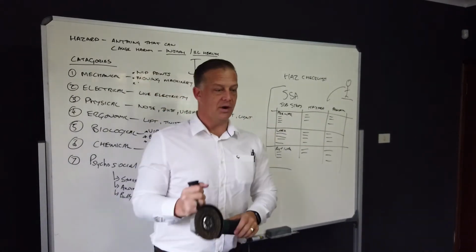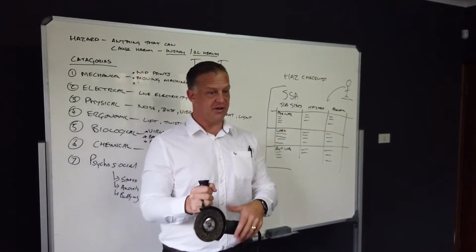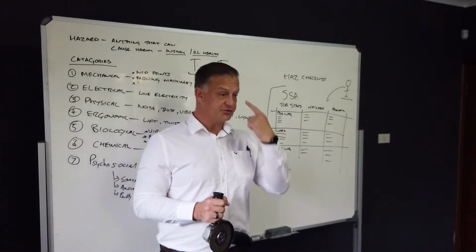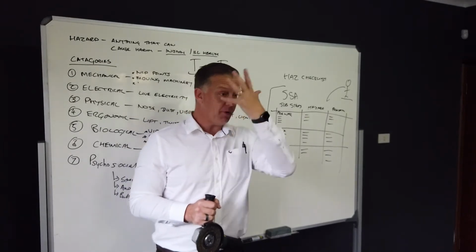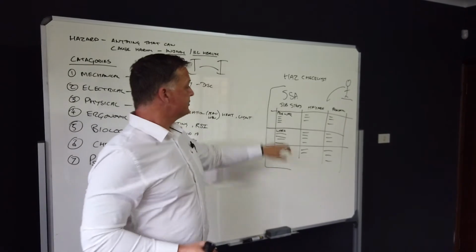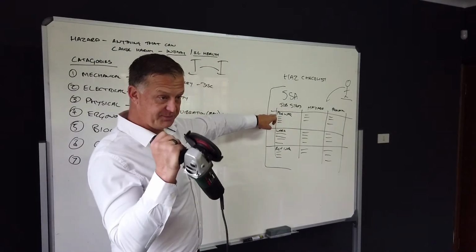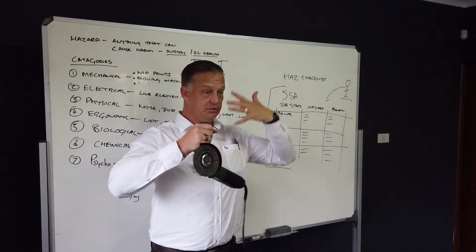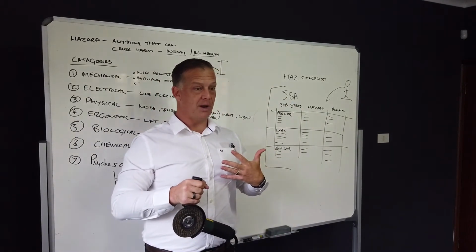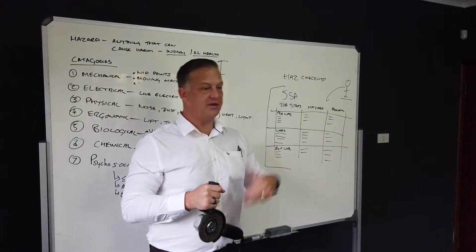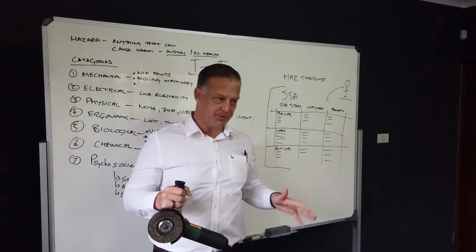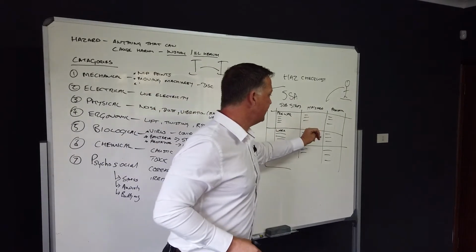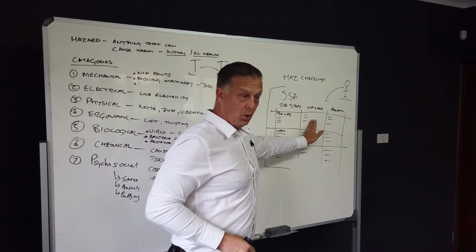Okay, so gloves. What else? Remember that the sparks created, what do you think I want to protect? Shield or goggles. Okay, so full face shield or goggles to protect my eyes and my face from sparks. So let's say pre-work, step one, inspect the equipment. Step two, make sure that the work area is safe. Step three is to put on all my PPE and make sure that myself and the other operators are safe. So this is a very simple approach, but just to break it down. So that would be three of the pre-use steps. And what we would then do is identify some of the hazards. What are the dangers?